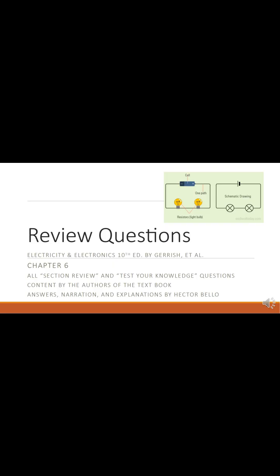Review questions, Chapter 6. What does a voltage regulator do for the lights in an airfield lighting system? It keeps the total voltage as required to keep the same current in all lamps, thus the same level of brightness. How much voltage will be found across a good fuse? No voltage or no voltage drop, since there is no potential difference between one end and the other end of the fuse. How much voltage will be found across a blown fuse? Total voltage or source voltage drop. A blown fuse is like an open switch showing total potential difference.